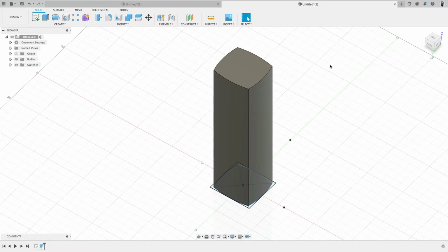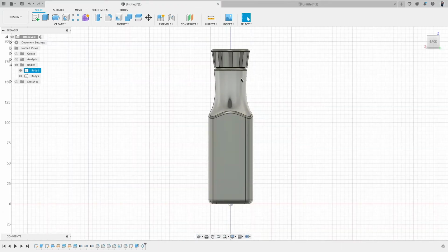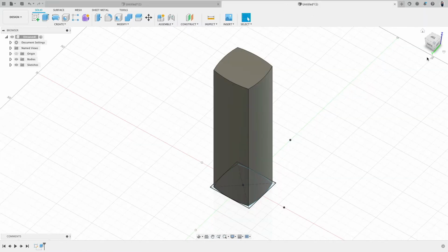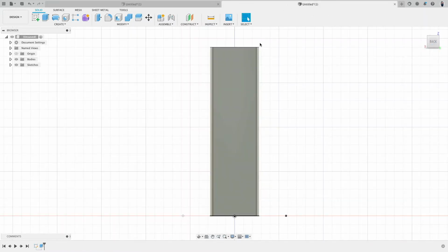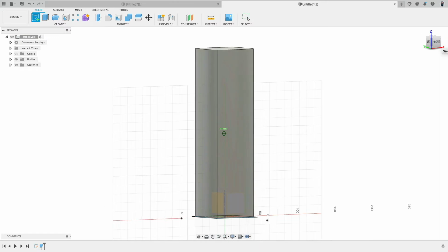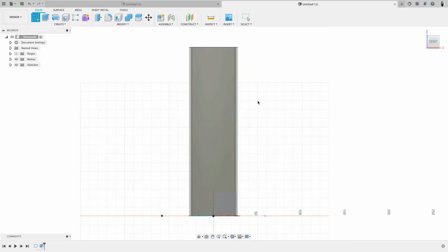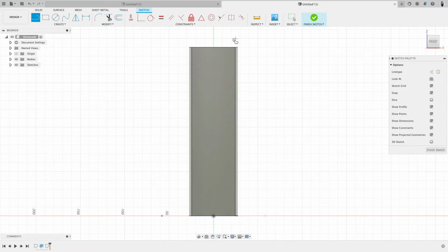Okay, nice. Now comes the wood lathe command. So we need a profile from the side, which we revolve and then cut. So sketch from the front, click on this grid, and then a horizontal and a vertical line, and then fit point, click, click. That's very good. Another line here. Okay, escape. Then this line we click and say construction.